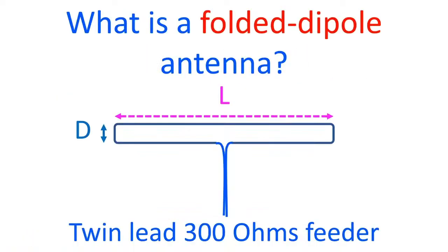In a folded dipole antenna, a half wavelength conductor is folded into a longitudinal loop and fed at the center. It has a higher impedance of around 280 ohms compared to the 70 ohms impedance of a horizontal half-wave dipole antenna. Hence, while a coaxial cable is suited for a horizontal half-wave dipole antenna, a twin-lead transmission line with about 300 ohms impedance is used for a folded half-wave dipole antenna. Half-wave folded dipole is commonly used as the driven element of a Yagi multi-element antenna.